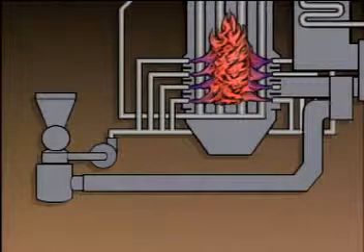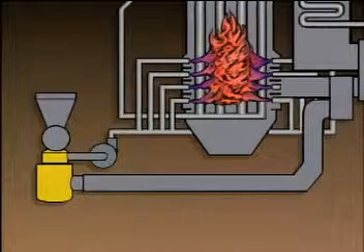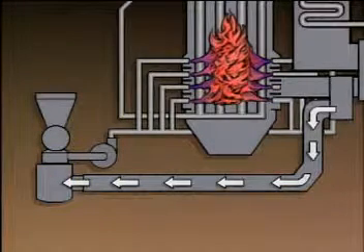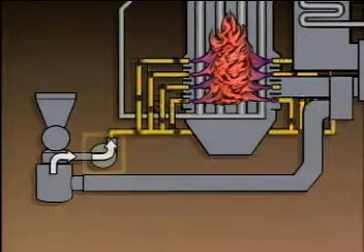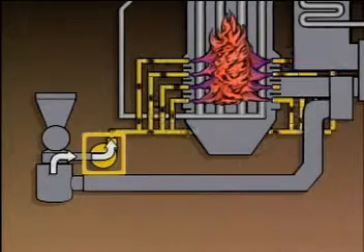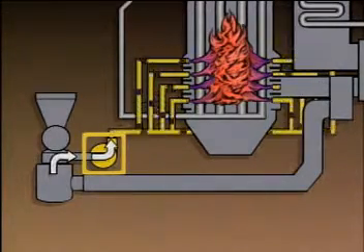Small chunks of coal enter the top of the pulverizer from the coal feeder. In the pulverizer, they are ground into the powder-like granules that can mix thoroughly with air. Primary air, which has been heated, enters the side of the pulverizer. The primary air picks up the finely ground coal, dries it out, and carries it to the burners. An exhauster is used to assist primary airflow from the pulverizer to the burners to help move the coal dust.